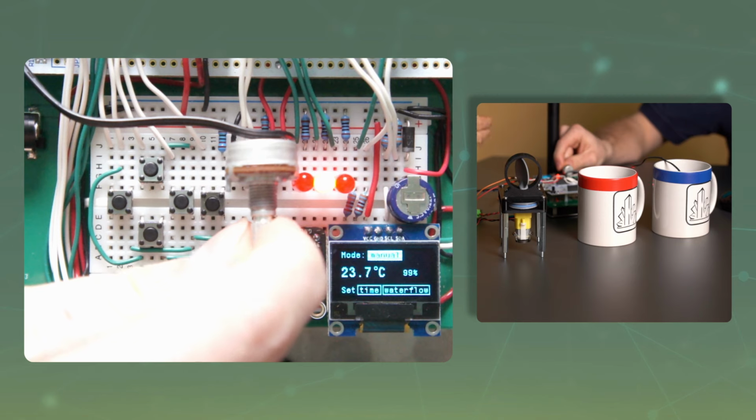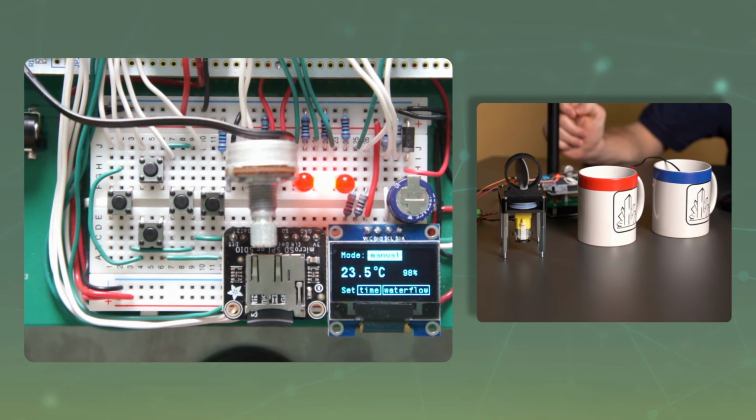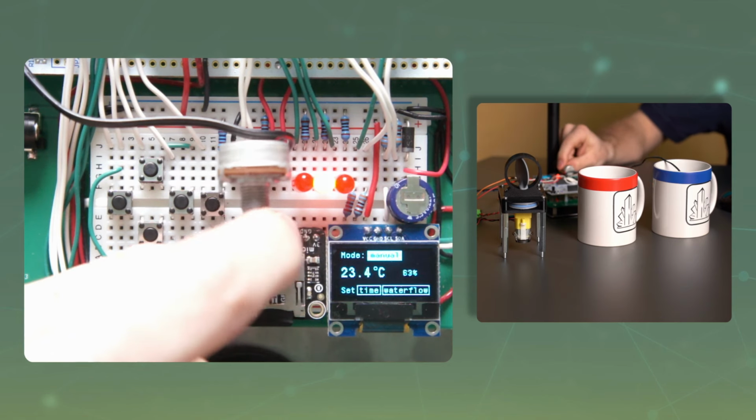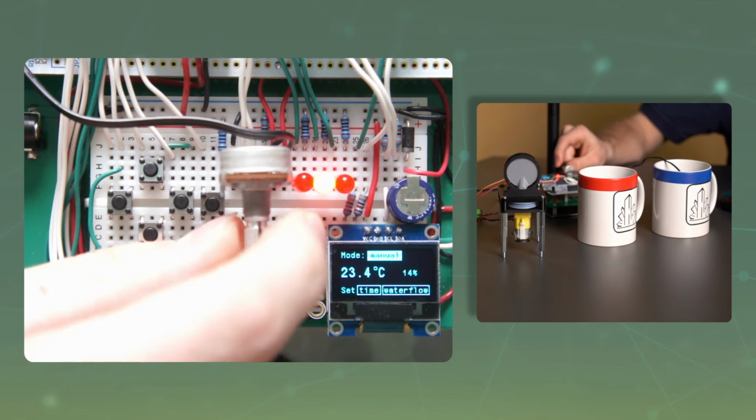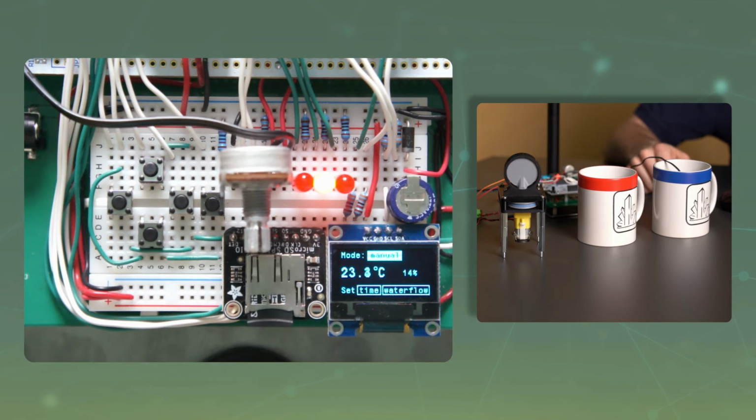At 100%, roughly 90 degrees. Because our motor is not a perfect model, it has a bit of friction, and in real life it would happen similarly. If we turn the potentiometer a little bit forward, we can see very nicely that it tracks the position, so most likely our position control is working well, because this control loop is already active at this point.